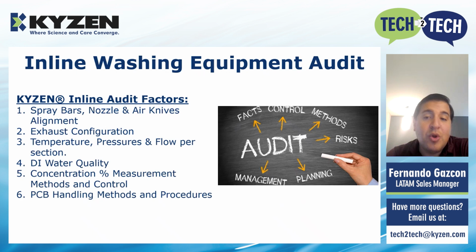Some of the factors we review are the configuration and alignment of the spray bar nozzles and air knives on each one of the sections, the exhaust system, maximum pressures and temperatures that your equipment is able to achieve, and quality of DI water being used in the process. This includes their water treatment plant in case they have one. We also review the best practices they should follow to take good care of each part of the process. Basically, we looked meticulously for potential issues that could be limiting the full capabilities of your cleaning equipment.